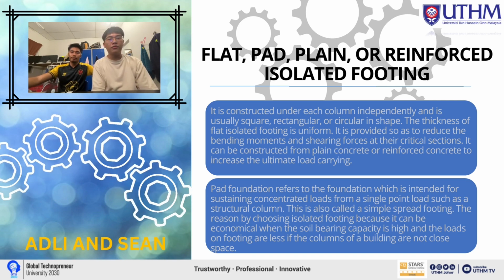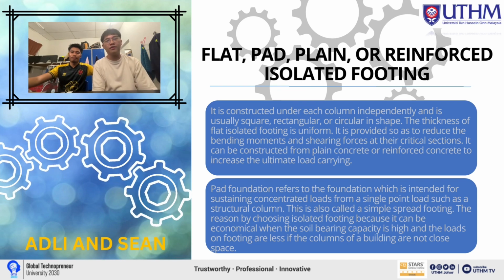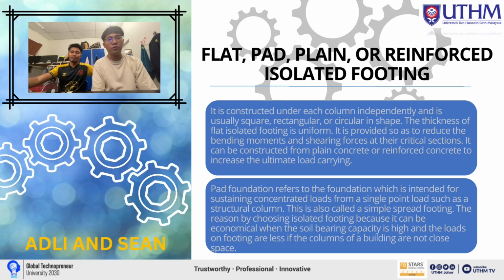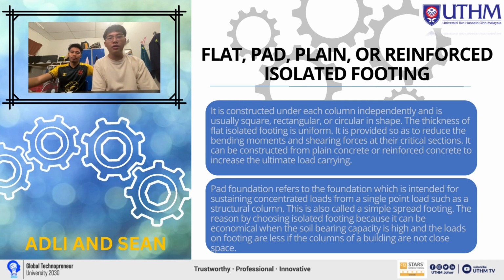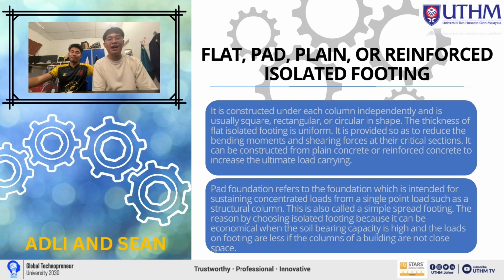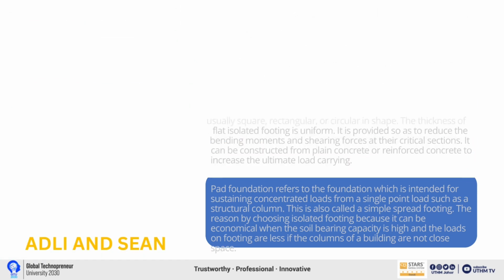The reason for choosing isolated footing is because it can be economical when the soil bearing capacity is high and the loads on the footing are less, if the columns of a building are not closely spaced.